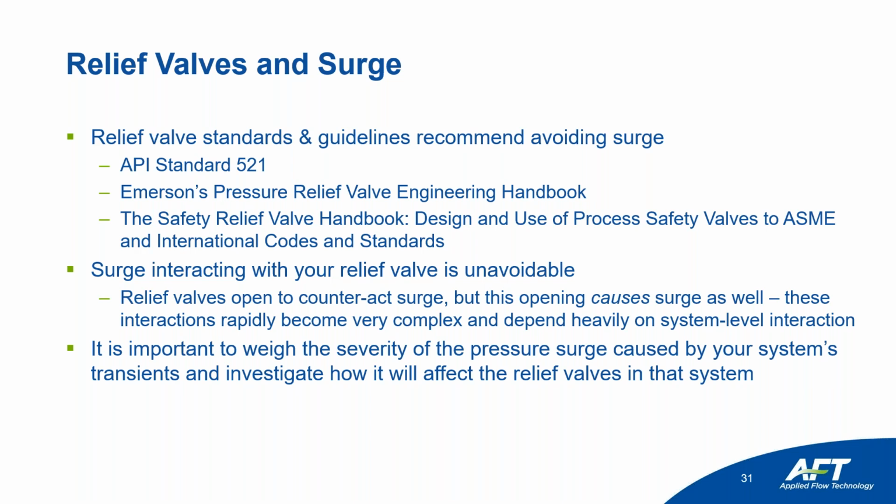But if you're in some kind of situation where surge and relief valve interaction is unavoidable, it can cause a number of different problems. It could blow out a relief valve. It could bypass the relief valve and still damage your system. It could cause the relief valve to chatter or flutter. And also could cause it to open up at the site of the overpressure.